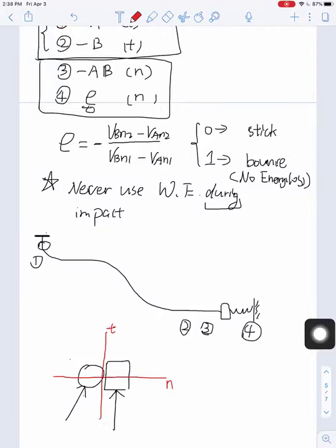If we call these particles A and B, particle A is traveling with a velocity that has an angle with either t or n. That tells you that you need to use trigonometry with any given information. Let's call that angle theta. You need to use that given angle to project the velocity or speed into both the t direction and the n direction before using any of those equations. And for block B, it's traveling in the t direction, so you don't need to modify that.